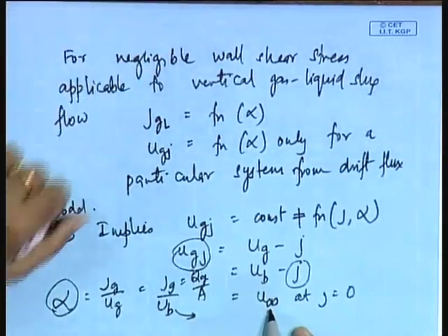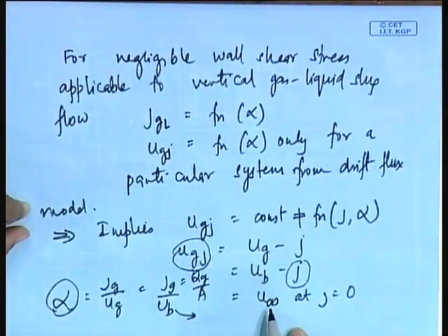If you get confused, you can use some other nomenclature for this. This is the velocity of a single Taylor bubble in that particular conduit characteristics. There is nothing infinite medium here, because remember one thing, in an infinite medium we will not have a Taylor bubble. Taylor bubbles are formed just because the gas is confined or constrained by the surrounding walls to flow through a definite space.